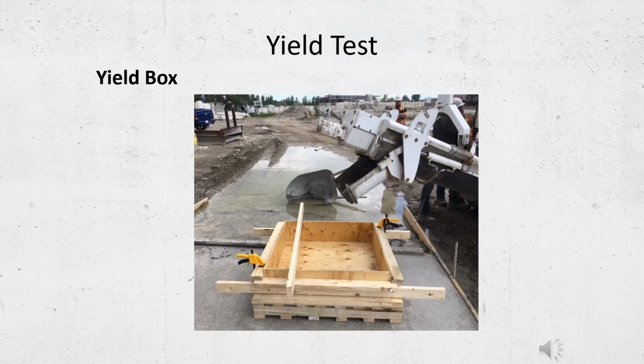If you don't have one of those designs readily available, please contact the consultant who certified your aggregates, who will most likely be able to provide you with a starting point. Knowing the flow rates of your materials based on the calibrations you've just conducted, you should be able to determine your counter set point to produce a quarter cubic meter based on the cement content with all the corresponding aggregate gate settings and admixture and water dispensing rates that go along with it.